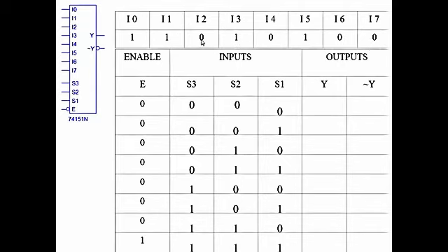These didn't come from anywhere, they're just made up. And we have our selection line, the S1, 2, and 3 is selection for which particular input we're selecting. So again, it's a binary number. We're going to pick, like this is 0, we're going to tie whatever's on the input 0 over to our output Y. And then we also have to look to make sure it's enabled. So the enable we're looking for, since this is a bubble, we're looking for a low. So the enable here is low.